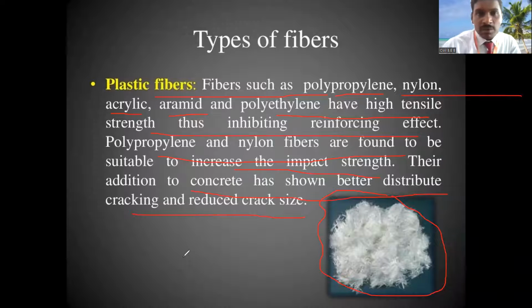So this is about plastic fiber. Plastic fiber increases the impact strength and shows better distributed cracking, so we can reduce the crack size.